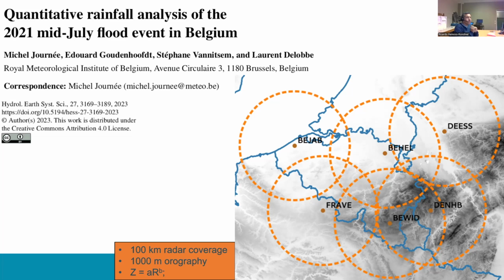Again, you mentioned a good point about different ways to calibrate and process, but maybe the differential phase is the one that could help us to avoid some of those issues coming from different weather met offices that maybe have their own unique processing chain. So KDP and specific attenuation could be one of our friends in order to do composites of rainfall rate, for instance. Thank you for the question again. Thanks, Ricardo.